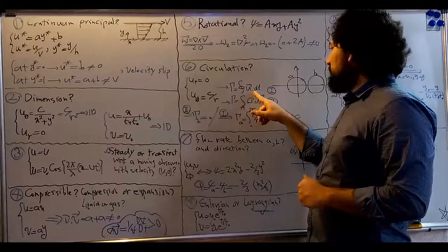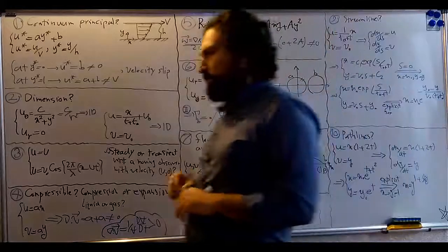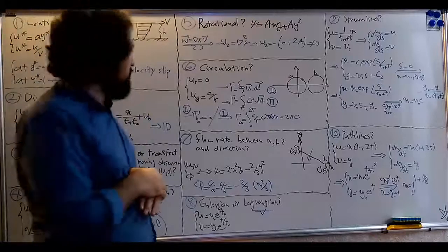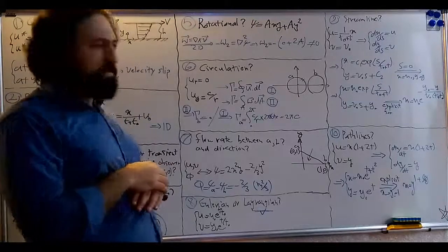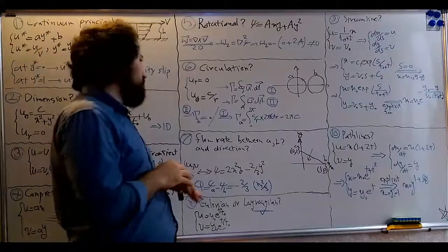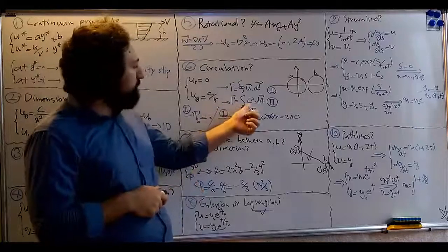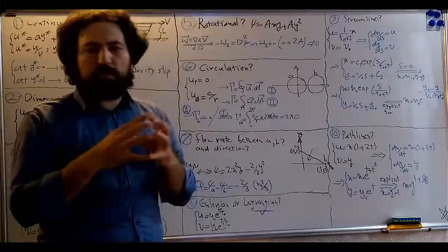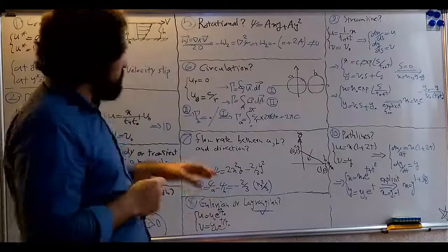The velocity dots the unit differential element parallel to the path. And using the Stokes formula, you can compute circulation using the flux of vorticity crossing the area inside that closed curve.